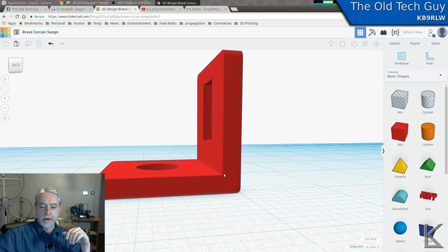And if we have a layer going right across here, that makes that a weak point. It would be much better to print this thing laying on its side. That way the layers are going to be stacked down it in this direction. And it's going to be solid beads of plastic that follow the shape. So that's going to make this corner a lot stronger.